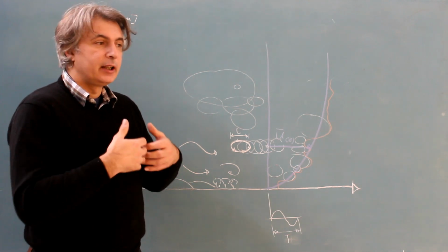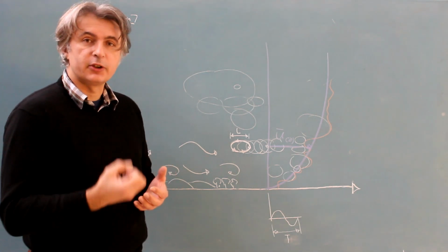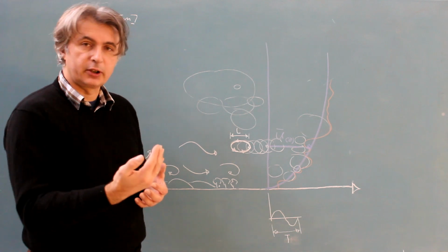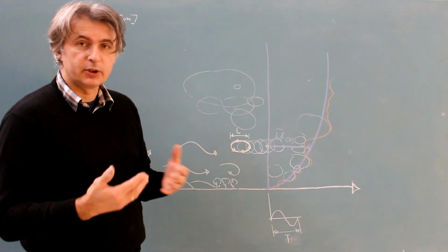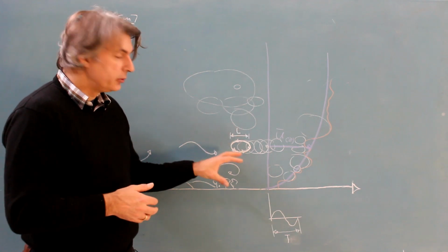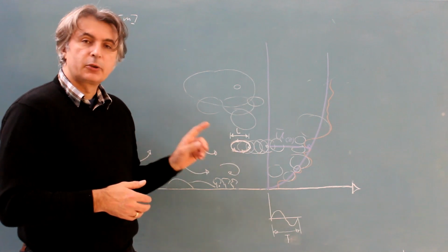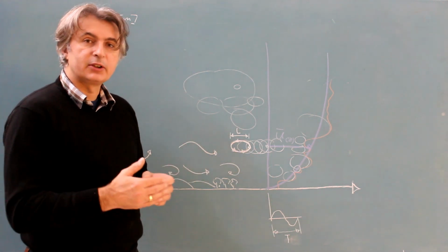And this is the input to estimate, if I have a structure with a certain eigenfrequency moving in a specific eigenmode, in a specific motion, that the energy, the contribution at the eigenfrequency of the structure, will create a certain resonant effect.